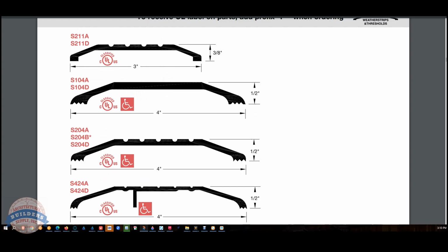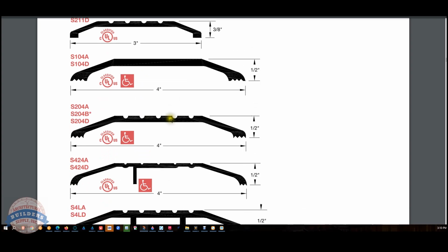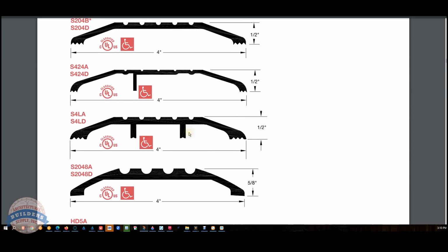I've lost my footing on a smooth threshold in the past. They're slippery when it's wet. A fluted threshold definitely helps, so some sort of treatment to the top. Also, a substantial enough wall thickness to accomplish the project, meaning you want the threshold to be durable and to do the job for which it's being asked. So a thick enough extrusion is what the manufacturer is going for.